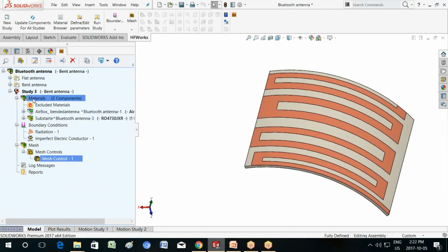So what we've just said is, whenever we do the meshing, I want the mesh to be automatically refined to this 0.1 millimeter, and that could give me, in one shot, essentially the required mesh for accurate results. So we can do that with one shot.